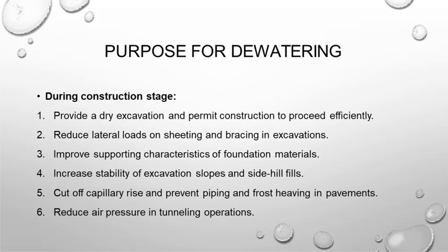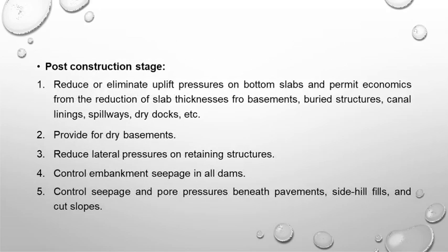So what is the purpose of dewatering? During the construction stage, it provides a dry excavation and permits construction to proceed efficiently, reduces lateral loads on sheeting and bracing in excavation, improves supporting characteristics of foundation material, increases the stability of excavation slopes and sidehill fills, cuts off capillary rise and prevents piping and frost heaving in pavements, and reduces air pressure in tunneling operations. These are some of the purposes of dewatering in a construction site.